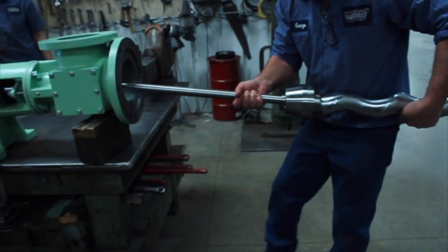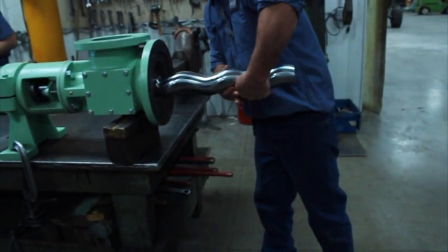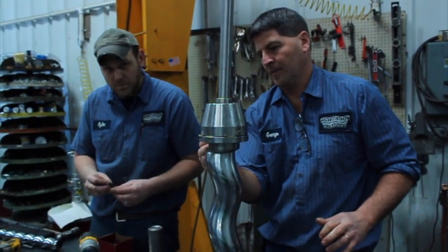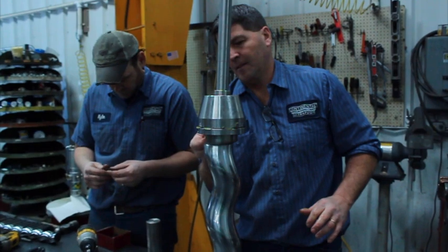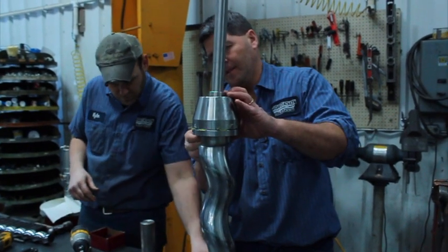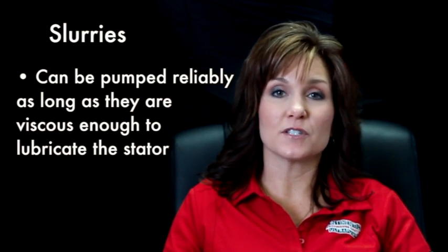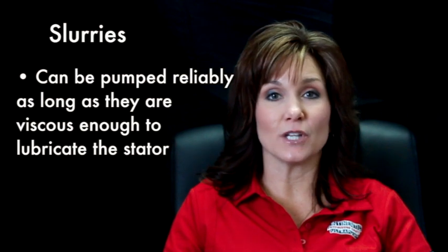The reason progressive cavity pumps are used is because they are durable with only one moving part, rated for longevity. In operation, our pumps are primarily a fixed flow rate pump and offer long life and reliable service, transporting thick, viscous fluids. Abrasive fluids can shorten the life of a stator, but slowing down the RPMs will help reduce the wear. Slurries can also be pumped reliably as long as the slurry is viscous enough to maintain a lubrication layer around the particles and protect the stator.